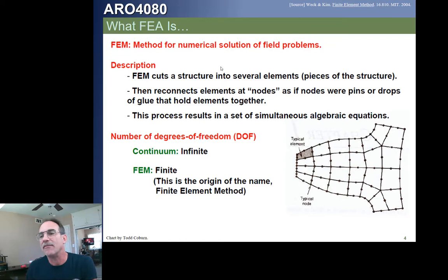Okay, we're going to have points. So in order to do this, first we're going to have to make a judgment call about what kind of elements we're going to use. And then we have to figure out where these elements are and how they connect together. Now, where they are is less important than how they connect together. But where they are determines what the boundaries of each element are, and then the program can figure out connectivity from just the locations and the way that your model ties them together.